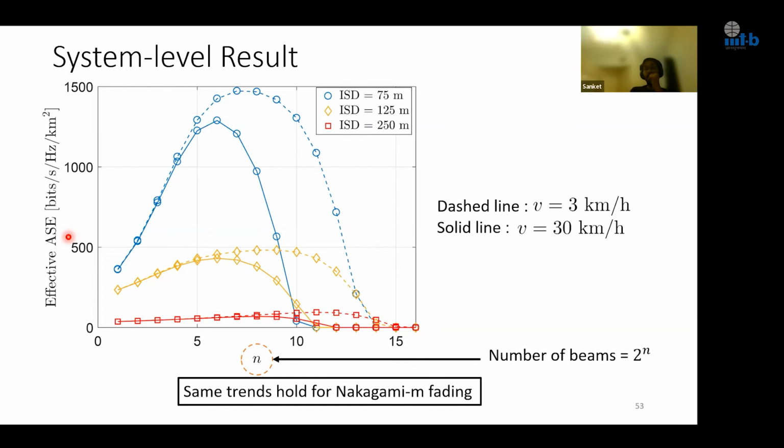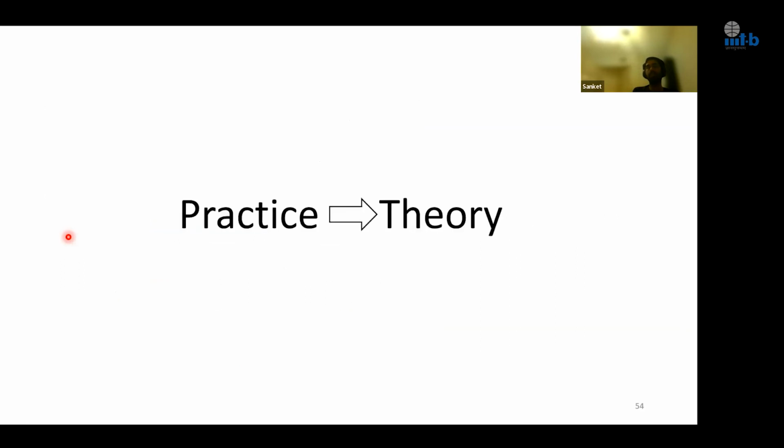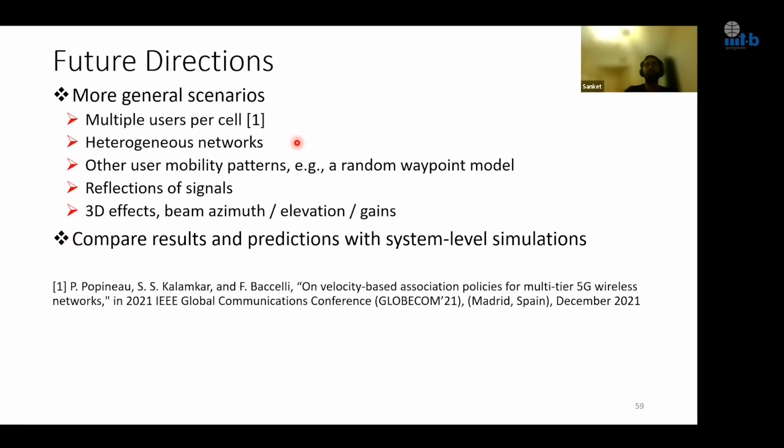Yeah, certainly. As I said earlier, what you're saying comes under heterogeneous networks. You have a macro cell operating at 700 megahertz and a small cell operating at 28 gigahertz, and their beams might overlap. I'm not sure whether one base station can operate both at the same time. But if we have different frequencies, there will be no interference, essentially, right? One beam is operating at 700 megahertz and another beam is operating at 28 gigahertz. So there will be no interference between those beams. Even though they overlap geographically, there will be no interference, because they operate at completely different frequencies. Does that answer your question?